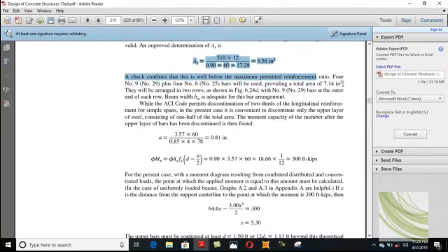4 number 8 bars are placed at the outer end of each row. The beam with bw is adequate for this bar arrangement, because these bars are placed in such a manner that they fulfill the minimum spacing criteria between the bars.